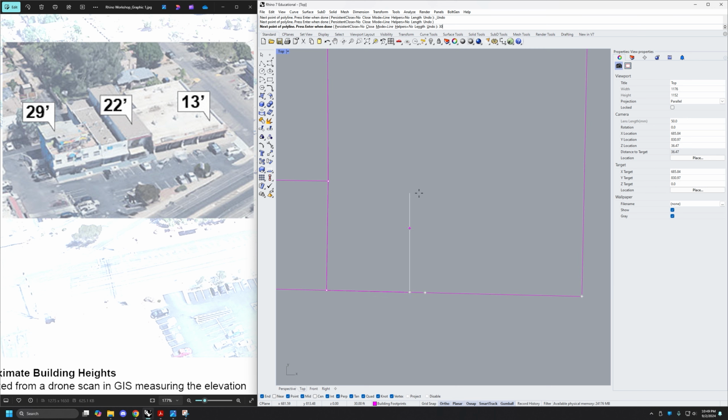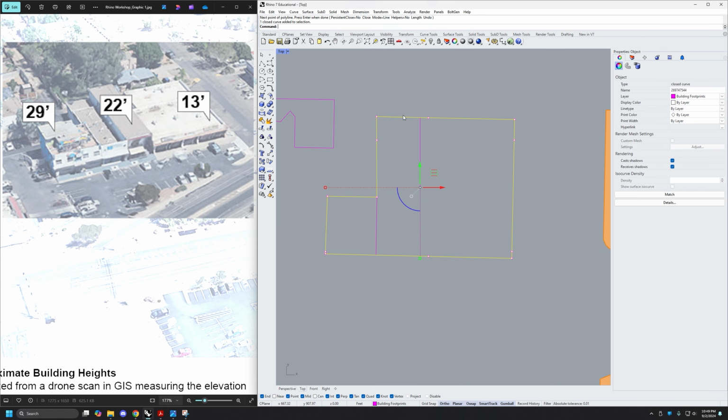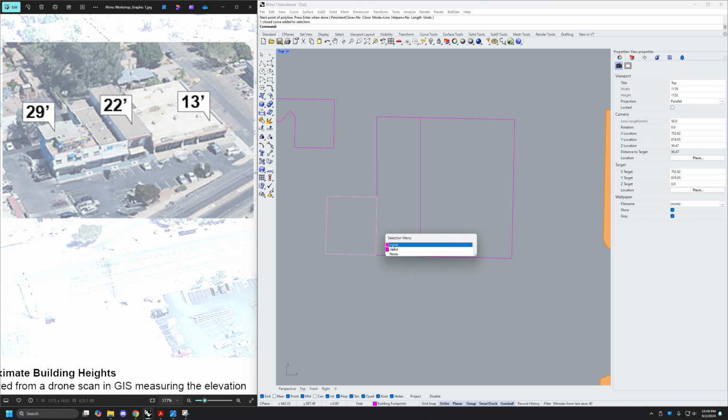Anyway, so I'm just going to keep continuing up here. And I think this intersection is fine. And then I'll end this polyline right here. Okay, cool. And then one last one. This can be easy. So we're just tracing here, here, here, and back home. Great. Okay, so now we should have our original line that was created by CAD Mapper. We've got our different curves.